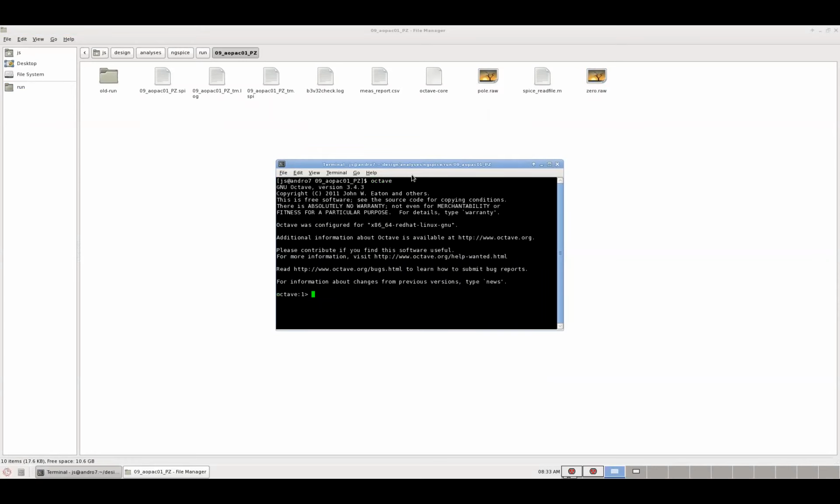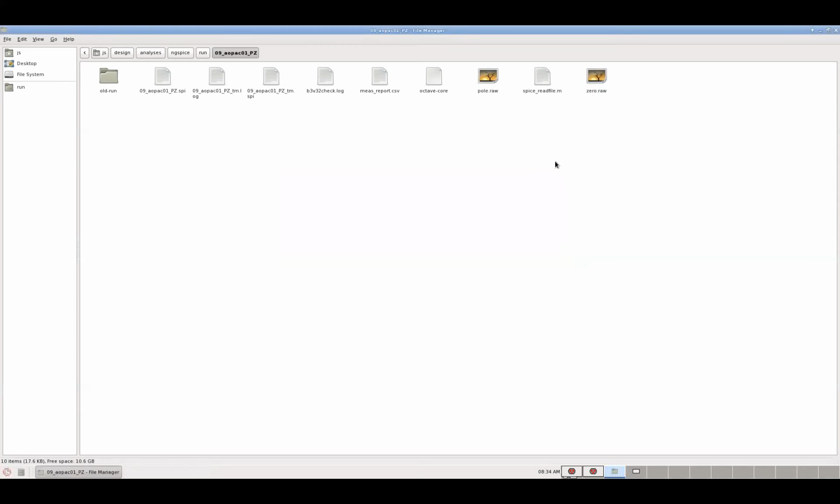and read this back using something called spice_read, which we are going to add for every user. If you start simulating henceforth, you can also use Octave to post-process your raw files. And that's going to be a feature that's going to be added by the end of day, by this evening, to be pushed to all users. That's pretty much it. But yes, you can run pole zero analysis and look at your poles and zeros uniquely in these separate raw files.